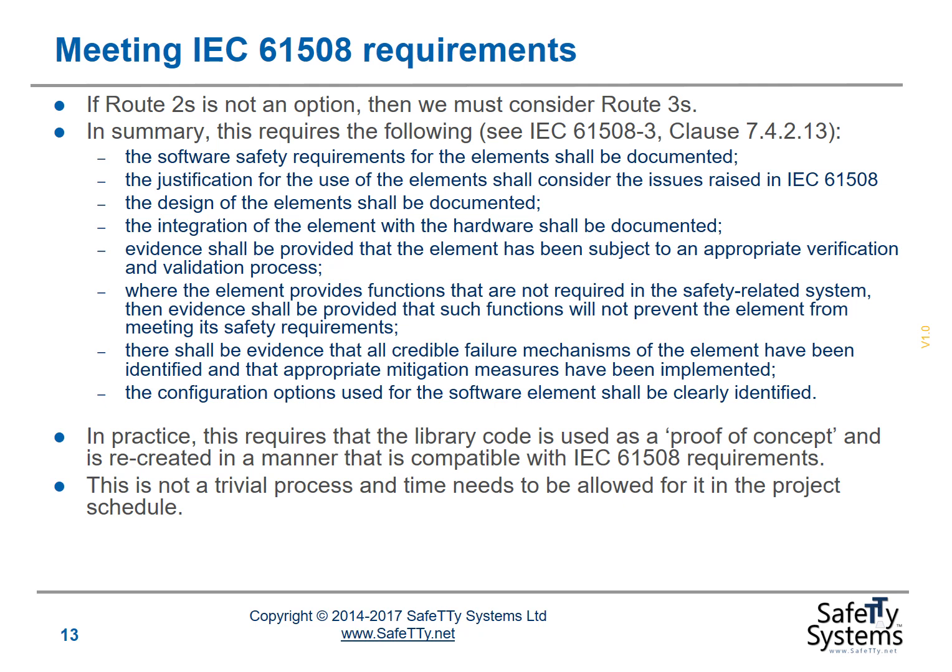What this means in practice is that existing library code may be used as a proof of concept, but it needs to then essentially be recreated in a manner that's compatible with IEC 61508 requirements. This is not a trivial process, and time needs to be allowed for it in the project schedule. In my experience, people often simply don't allow enough time to do the required work on the software libraries in the development process.